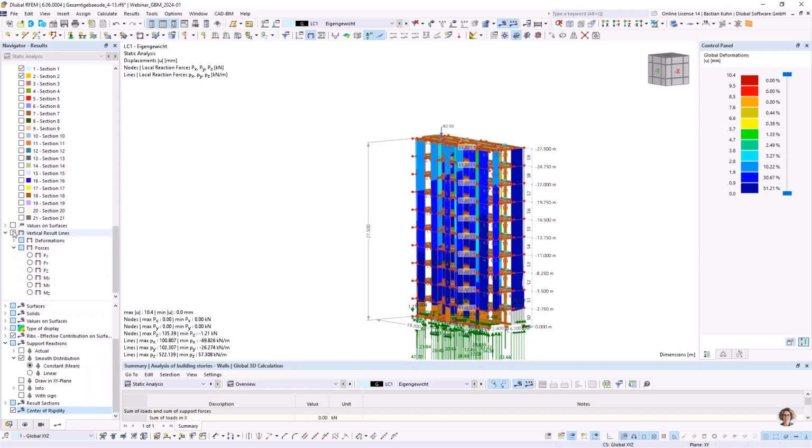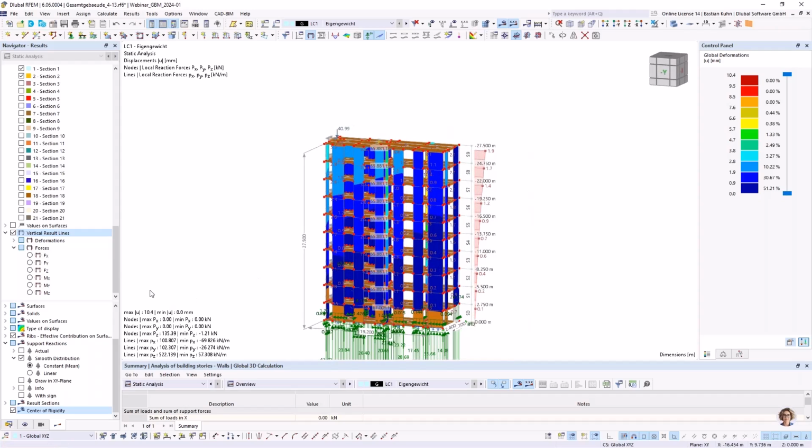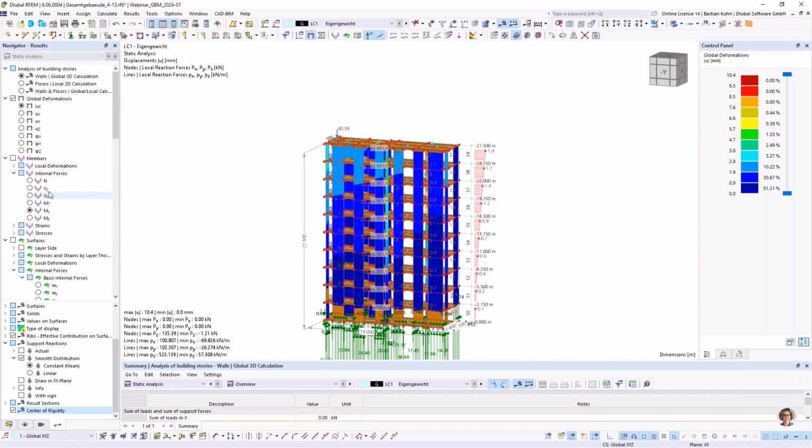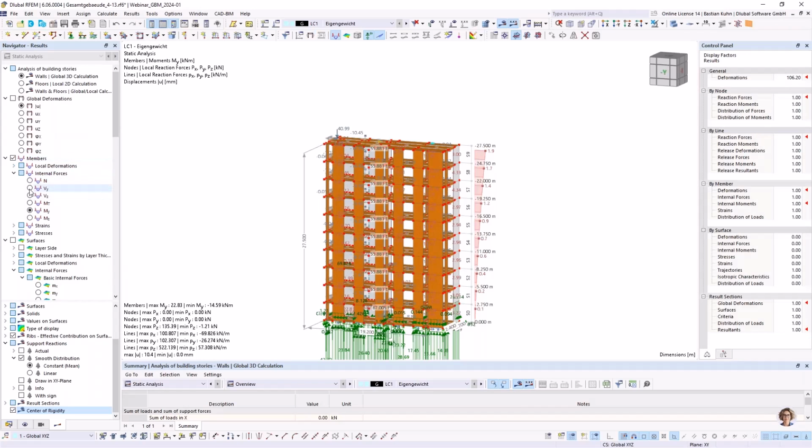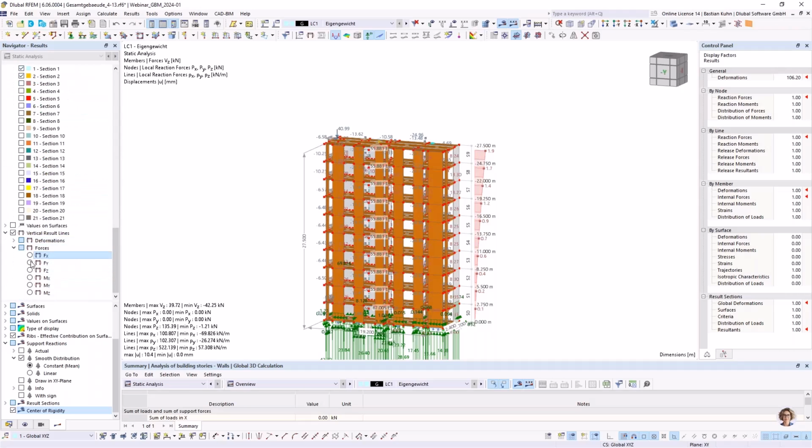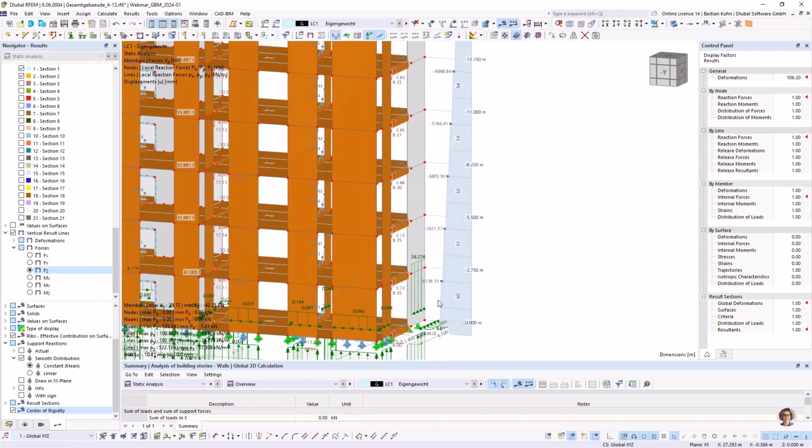We have vertical result lines. So you see graphically the horizontal force when you activate it. Okay, sorry. Where is it? Hold on. Here, this one, this one, this one. Yeah, so you have the horizontal force in here. Of course, on the bottom you see the complete force that's going through the whole building. Also something that you would need for the dynamic analysis.